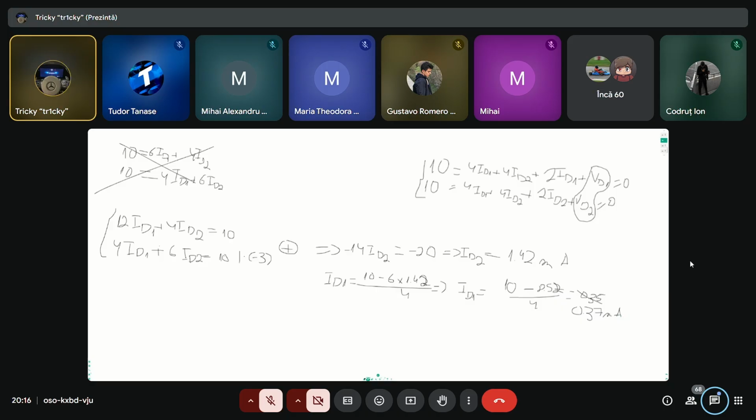Okay, nice. So what do we do now? Let's calculate VD1. VD1 is equal to same thing, 1.2 times 0.025 ln of what was ID1? 1.42 divided by 10 to minus 8, and this results in